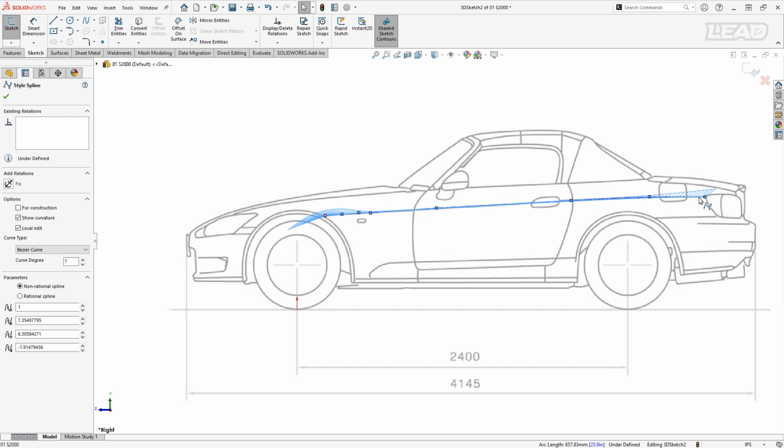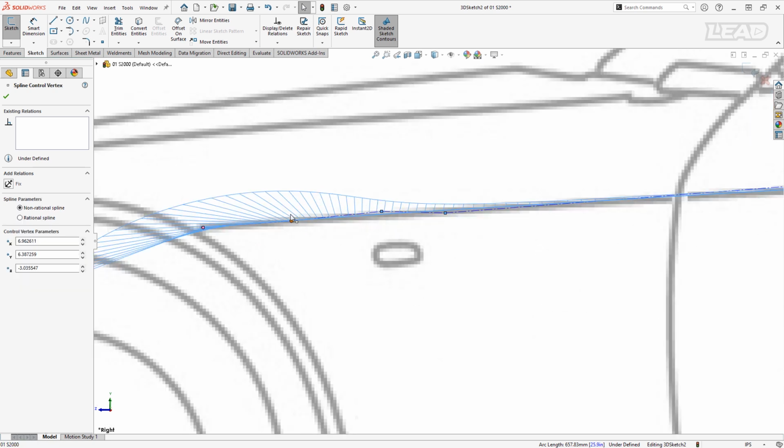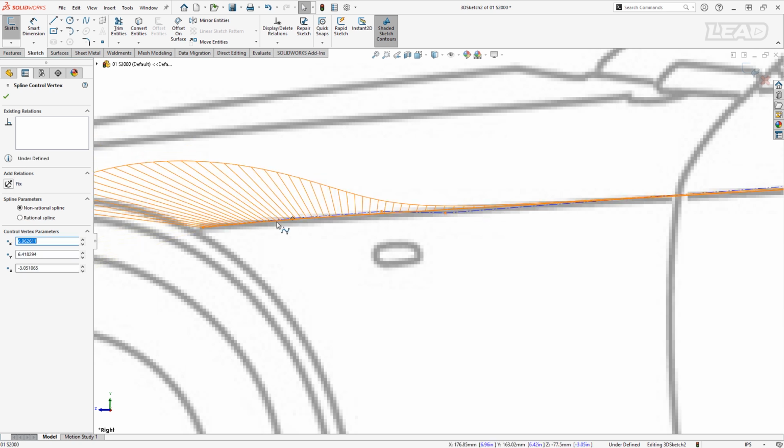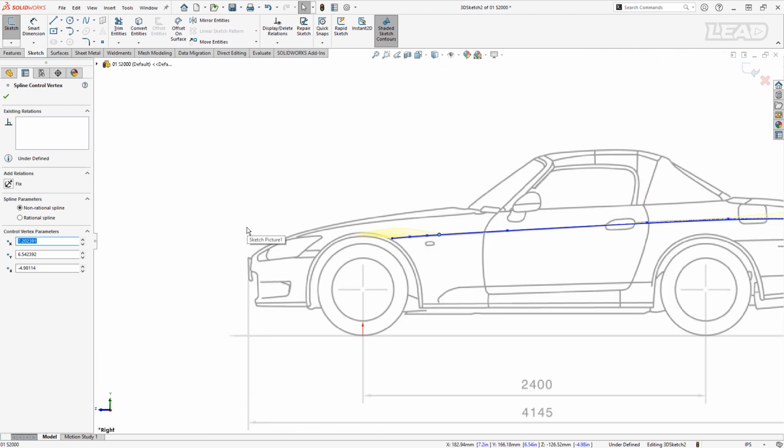the back. And what this means is that those points are not in line with each other, which again, depending on what you're modeling, doesn't necessarily mean a bad thing, but it is something that we need to be aware of, especially as we manipulate this around and we watch these curvature combs. We've got these points going up and then this one coming down. That's generally going to be a bad thing. That's something that we want to avoid. We want them to all be fairly gradual.